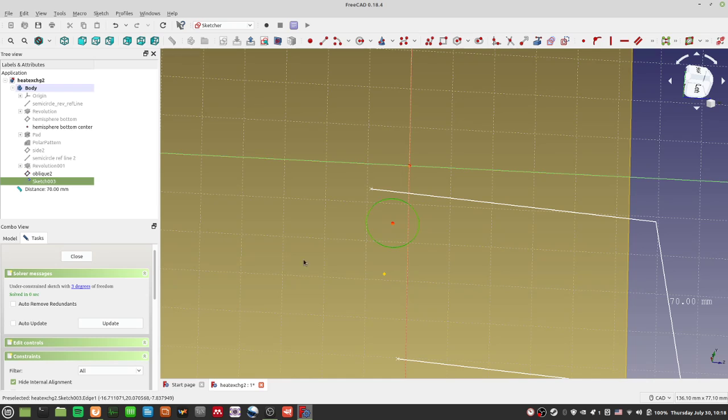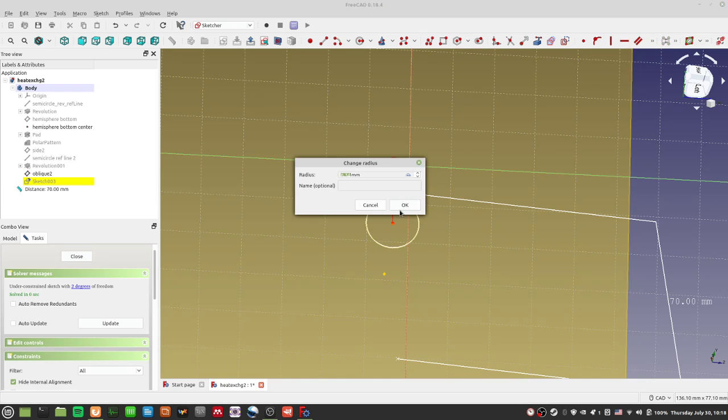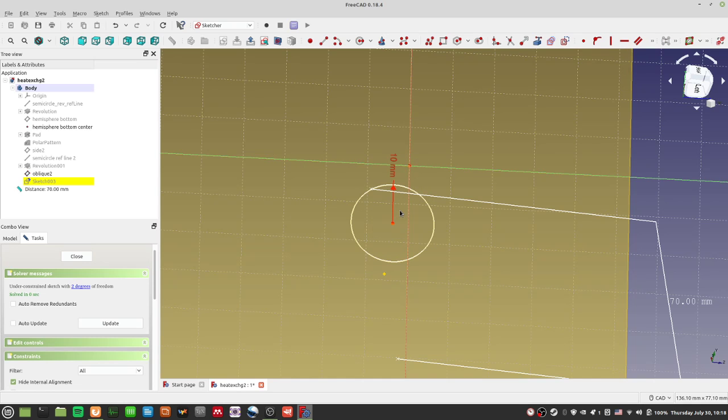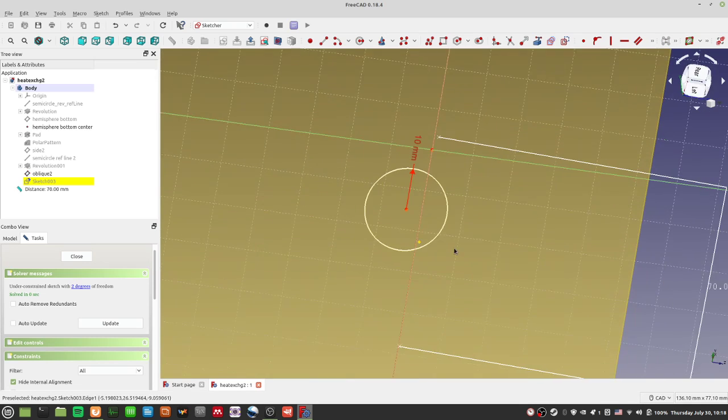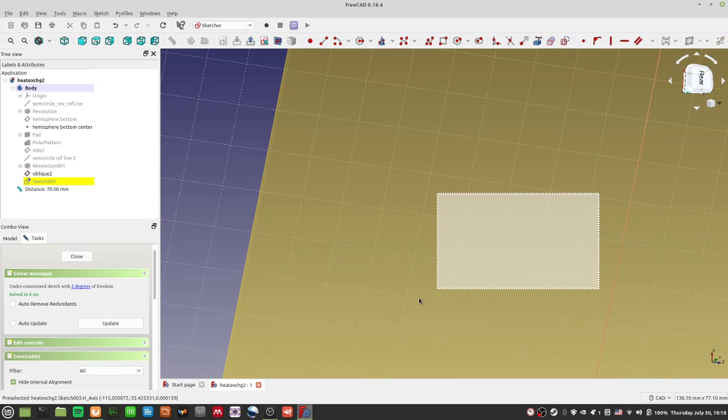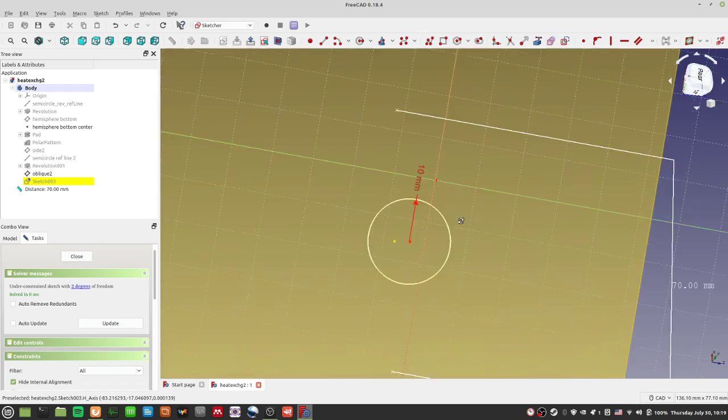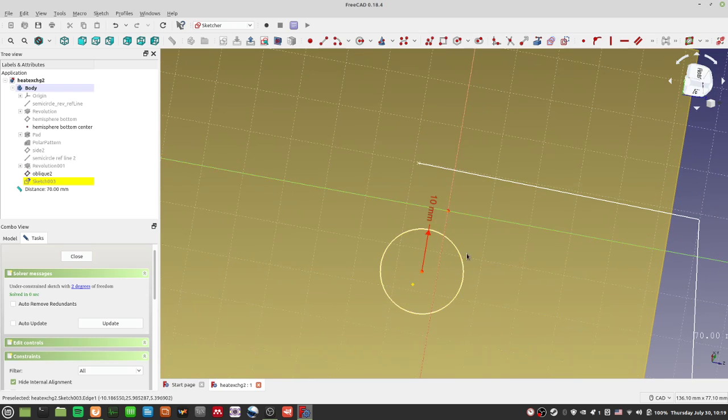Anyway, I want to make this circle have a fixed radius, and I'm just going to do 10 mm radius, because the flow rate through this pipe should be somewhat bigger. I can shift it as and how I like, but this is what I'm fixing it to. Next thing I want is to fix this point and this point, because I really want to fix this circle right here. I don't want it to move. So I will fix these 2 points to be a certain distance.